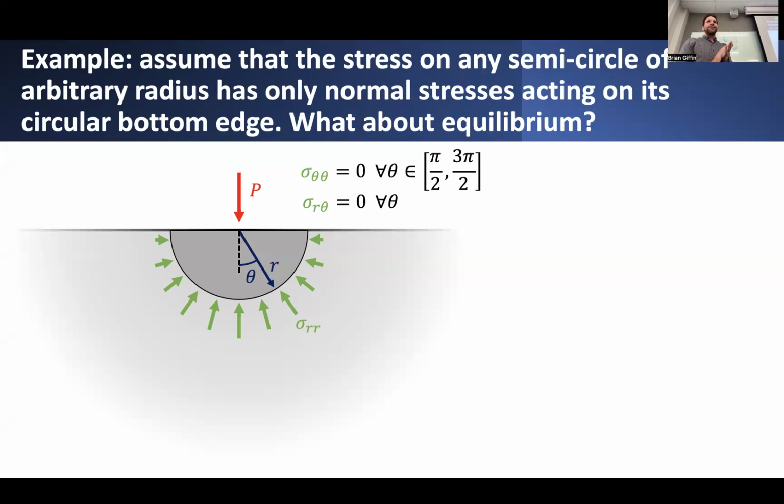All right. So for this particular problem, we are going to have to be a little bit more creative in how we come up with the boundary conditions. Suppose we did actually consider this as an infinite plate. How we actually define boundary conditions on an infinite domain is kind of anybody's guess, because what exactly is the boundary of an infinite domain? We can certainly define the boundary conditions on this top surface. It has to be such that there are no components of traction acting on this top surface. So the normal component of stress and the shear component of stress have to be 0, except at this point of application of loading.